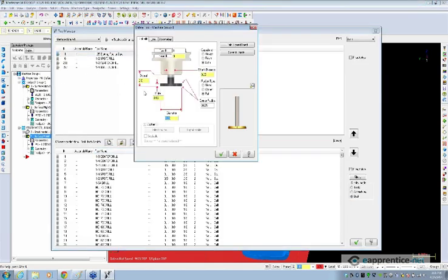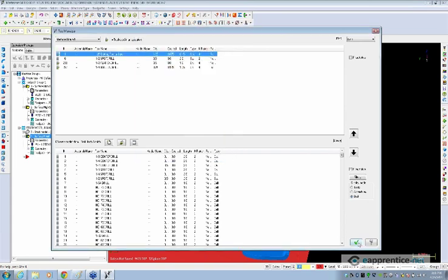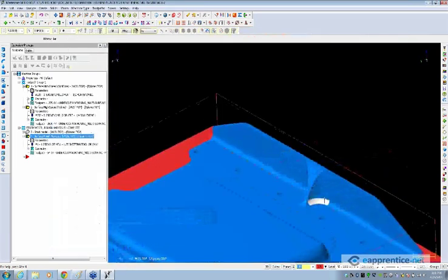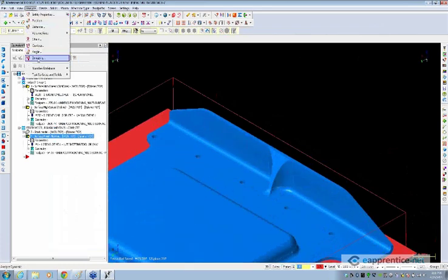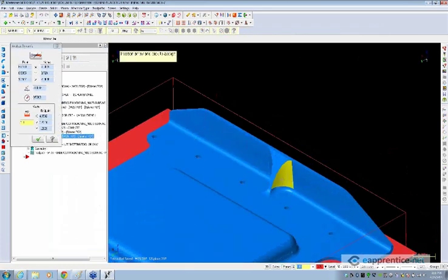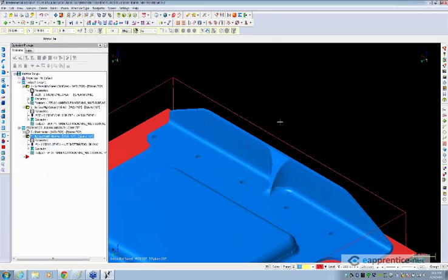So what I'll do, we've got our 1.25 slitting saw, but keep in mind that, what is this, 150 thousandths thick means there are two 75 thou radii on either end. So that actually shrinks down the total diameter here. Now, we may actually want to use a slightly smaller tool, but that's also going to depend on what this fillet radius is here. So if we do Analyze Dynamic, you notice this is a fillet radius of 1/2 inch, so we really need to choose something 1 inch diameter or smaller to be able to successfully cut this.